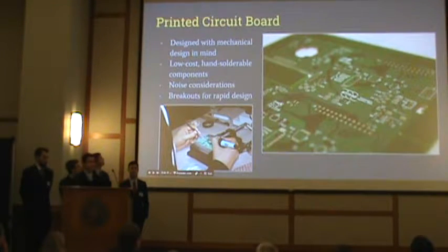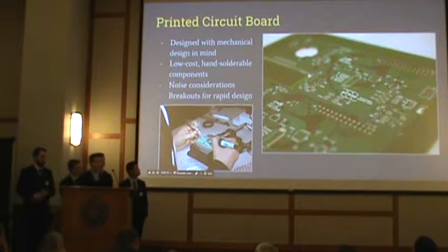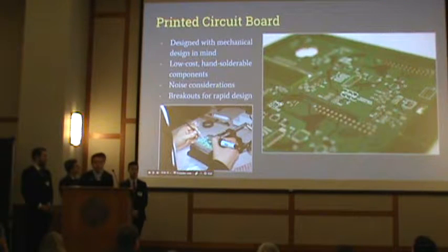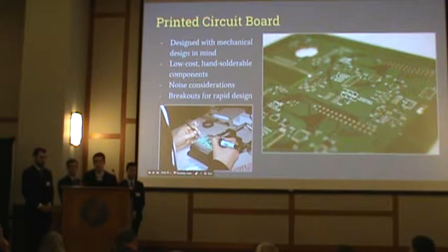Then, to satisfy those mechanical constraints of portability and discrete packaging, we designed our own PCB. So, some things to note here, we had some unique cutouts to really satisfy that portable design and to facilitate airflow. We also separated the noise and measurement stages, or the especially noisy stages such as power conditioning, and the measurement stages like the high precision ADC that we were using on the PCB, and stuffed it all ourselves.